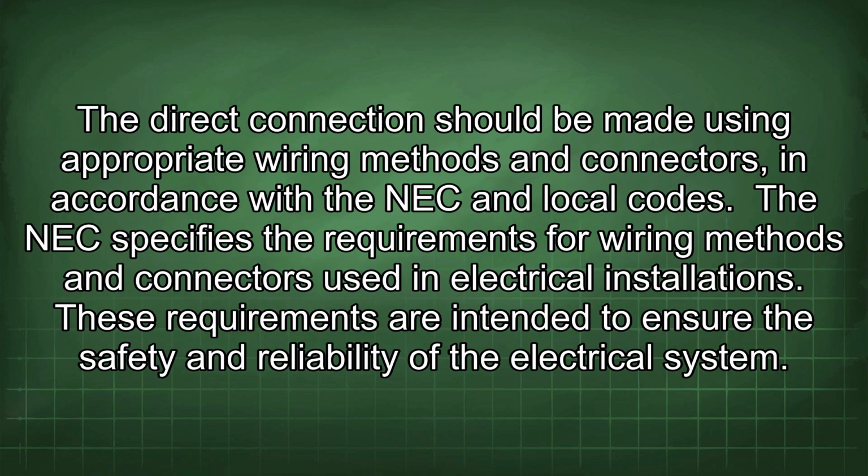It ensures that the emergency lights will remain powered during an emergency. The direct connection should be made using appropriate wiring methods and connectors in accordance with the NEC and local codes. The NEC specifies the requirements for wiring methods and connectors used in electrical installations. These requirements are intended to ensure the safety and reliability of the electrical system.